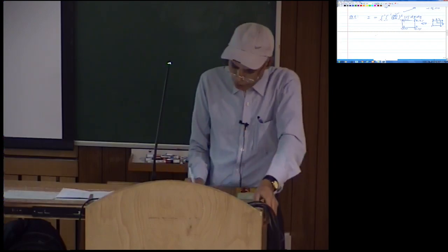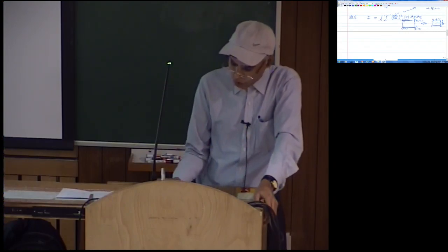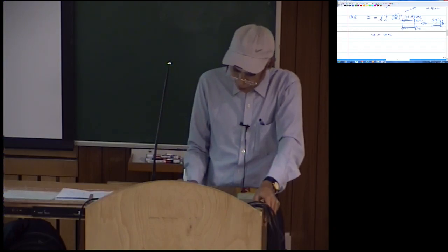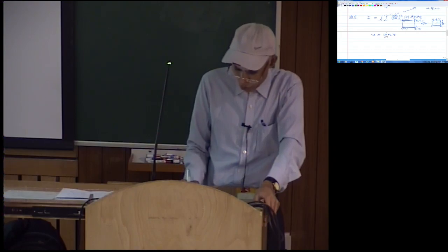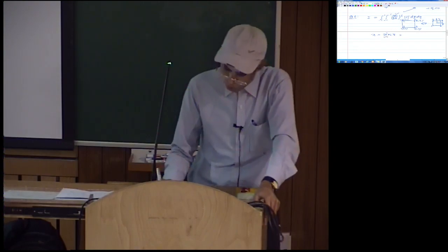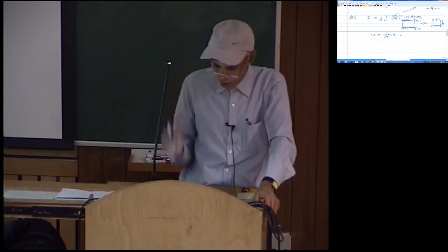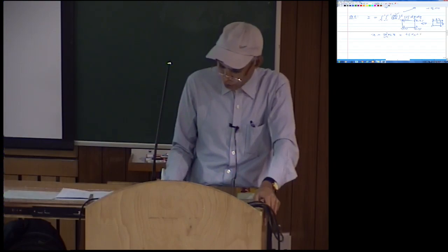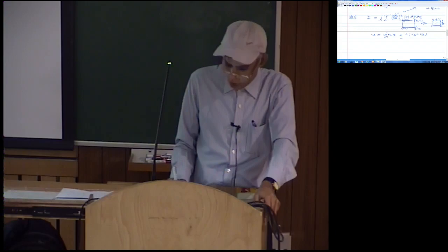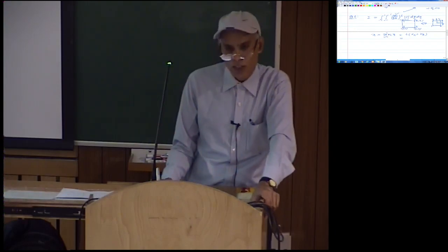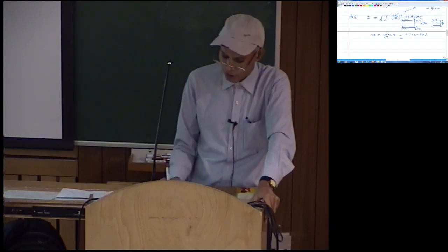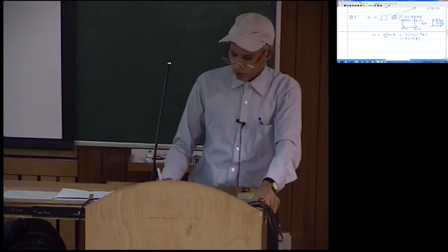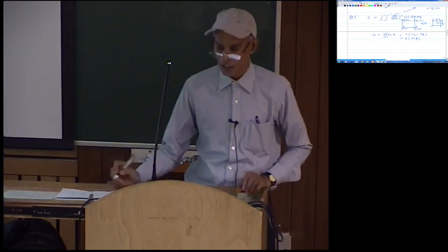So first you write your x, so obviously these are the x1, x2, x3, x4 coordinates. x is the summation of Ni xi over i going from 1 to 4. As you see, the x coordinates of only node 2 and 3 are non-zero, which are actually 4 and 4. So this is simply 4 into (N2 plus N3), and when you put the expressions for N2 and N3 for the 4-noded isoparametric element and simplify, this comes to 2 into (1 plus xi). N1, N2, N3 and N4 are shape functions.